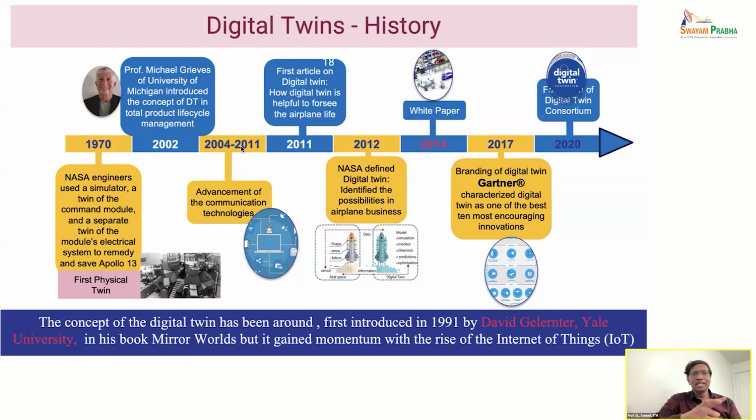And then what it will do is, if it is not a micrometer but maybe 100 micrometers, if the tool is worn out, I'll make the tool move further so that the size I finally get is the same as what is required. So that step is required. But in our factory, we didn't use that yet.